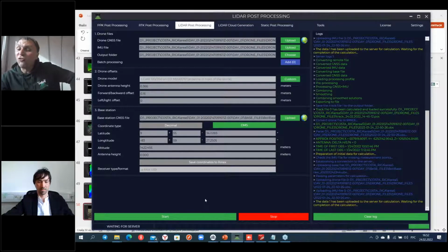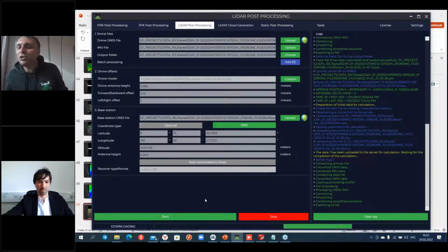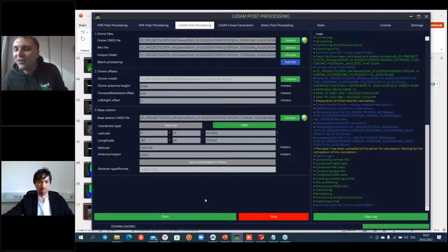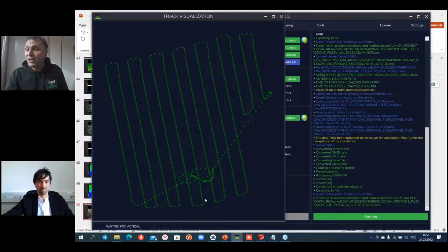The main parameter of a LiDAR is the penetration of the forest, the quality of reflection and the quality of your LiDAR. It doesn't matter how many returns you have, but if you get a noisy point cloud, it will lead to error. In this case, I would suggest using a Velodyne sensor because it penetrates forests in a better way. It provides a less noisy point cloud, and if you compare with solid-state lidars, the point cloud will be much better.